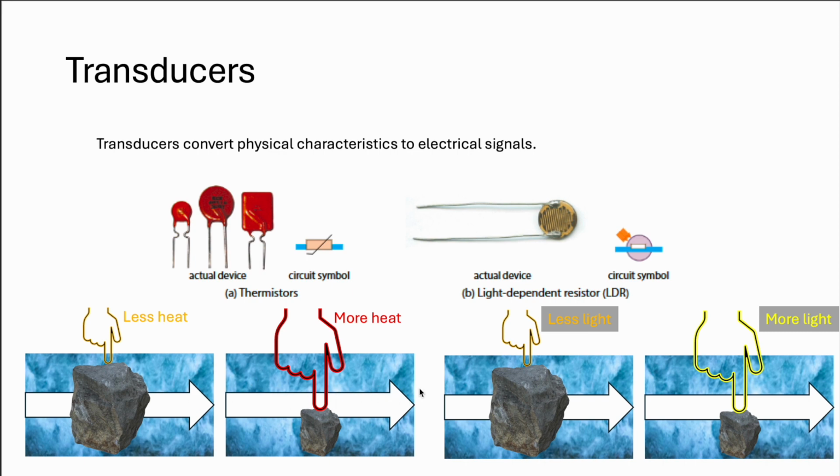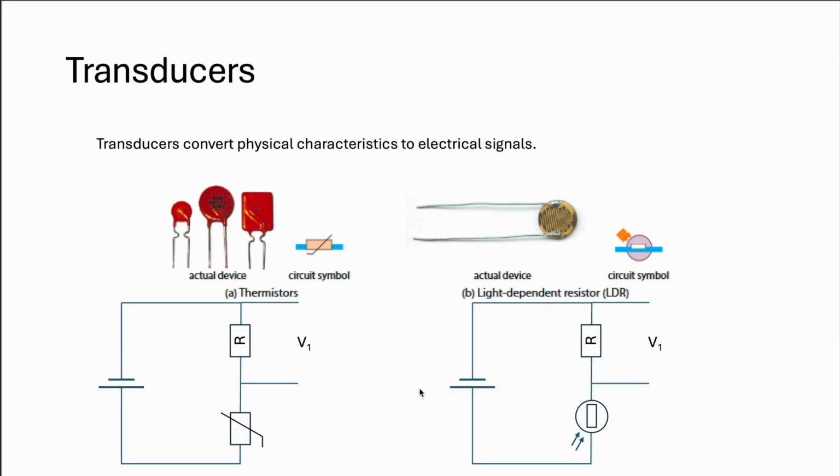So it depends on how the circuit is being set up. A variety of different outcomes can be designed. We can play around with heat and light for different kinds of outcomes using these two components. So you can use it in a potential divider. When there is higher heat, more current flows through, lesser resistance. So your small over big is going to be affected. Then you need to take all this into consideration.